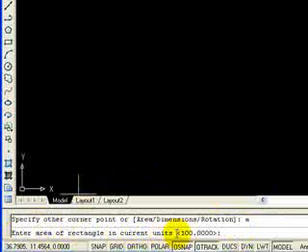You'll notice another little option here, which is going to be the default. Anytime you see these greater than or less than brackets, that's what AutoCAD is assuming that you want to put in. It's made some assumptions here since we've just started a brand new drawing, but let's go with it. It assumed 100, so that's going in as a default. If 100 is okay, I'm just going to hit enter and allow it to pick 100.